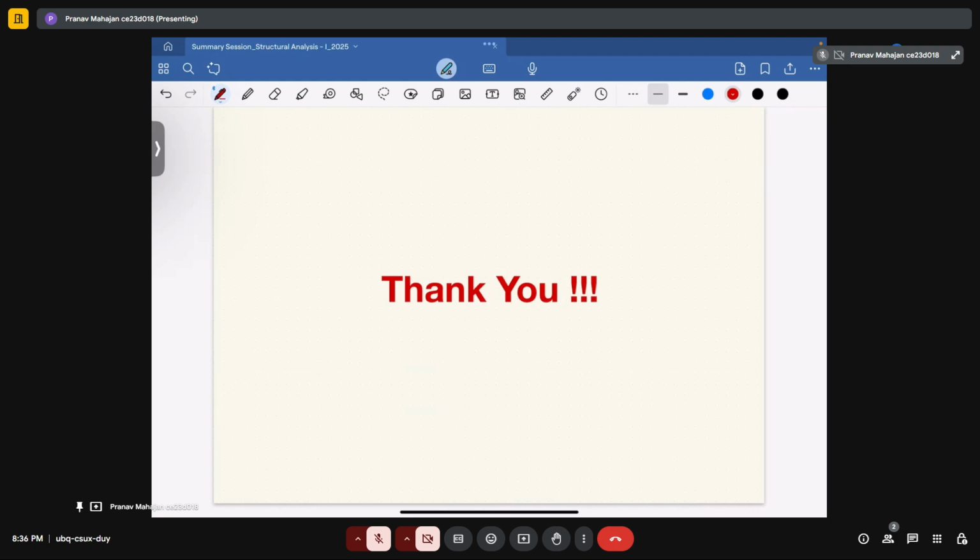After that, we have seen the trusses, and how you will analyze them. That means you have to determine the forces in the members of the trusses using two methods: the method of joints and the method of sections. As I already told you, when your structure is very complex, you will use the method of sections when you are expecting to calculate only one or two member forces. But when you are expecting to calculate all the member forces, use the method of joints, because that is easy for you. You just have to apply the equilibrium equations and get the value of forces.